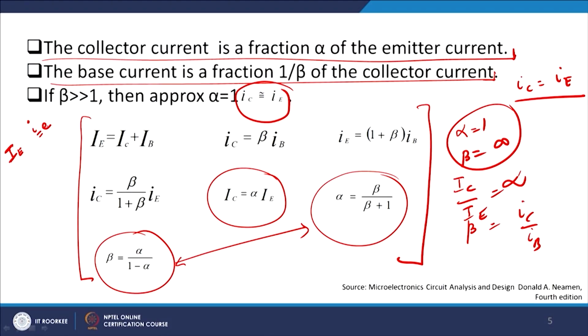Similarly, when the subscript is capital you are getting a DC bias, and small means you are doing a transient analysis. So you should be very careful when you use these. If I have small i and capital C, it primarily means that I am using a small signal AC analysis, but I am trying to find the total current flowing through the circuitry. So this notation is quite important in understanding this basic principle.